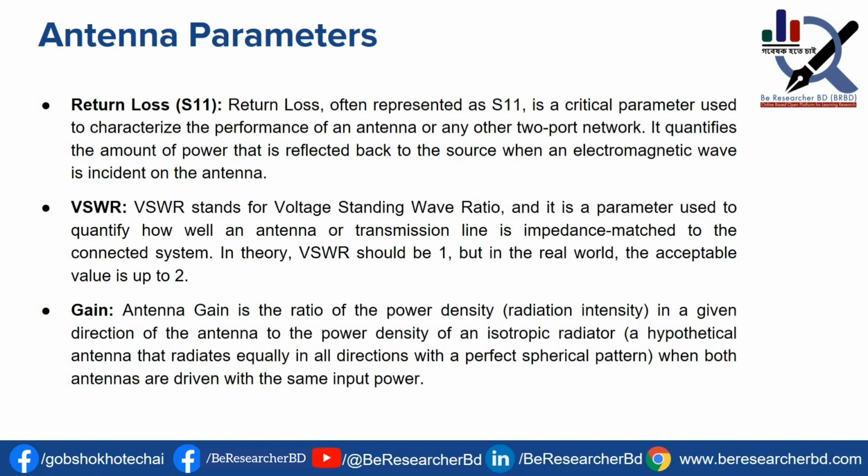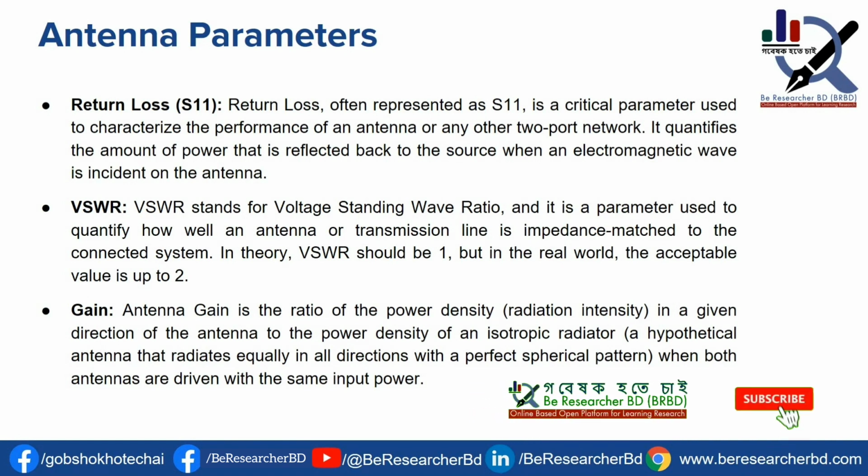Another important parameter is voltage standing wave ratio, or VSWR. VSWR indicates the impedance matching of the antenna and the system. From the maximum power transfer theorem, we come to know that when two systems have identical impedance, the maximum amount of power transfers from one system to another. VSWR should be 1, but in the real world, any value up to 2 is acceptable.